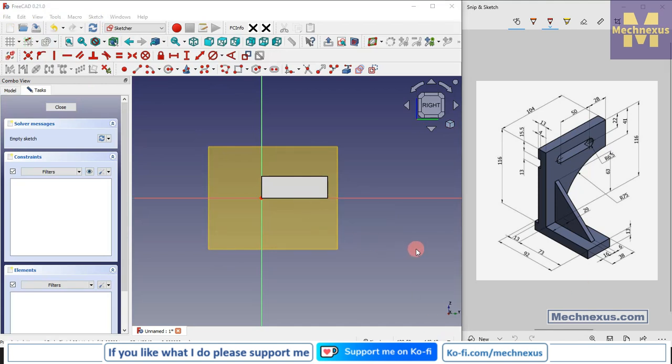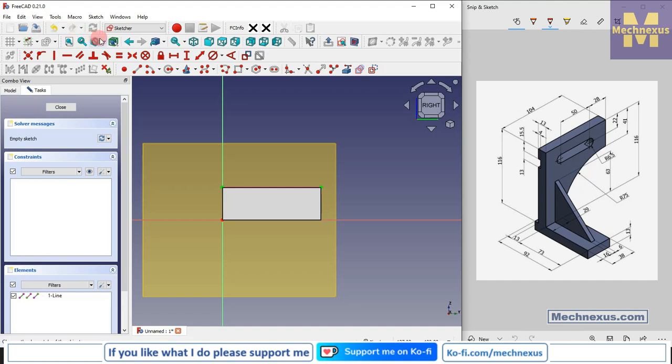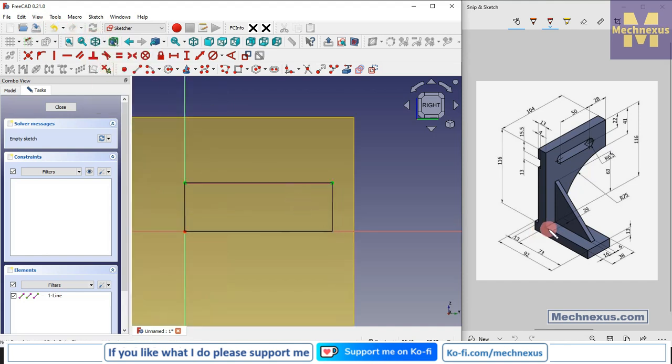Now select the datum plane and click on the sketch, and press the isometric view. We will select this edge and project it. And now we will switch to the right plane, and from here we will switch to the wireframe.